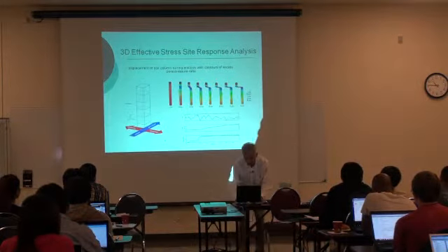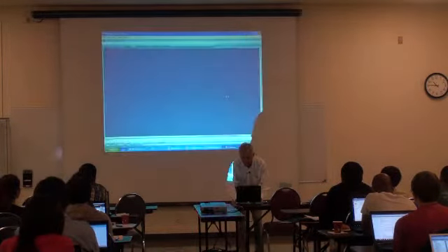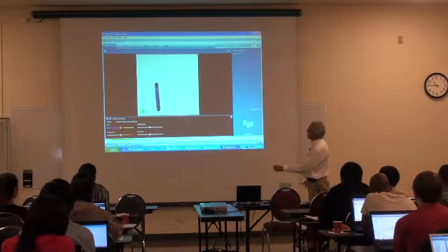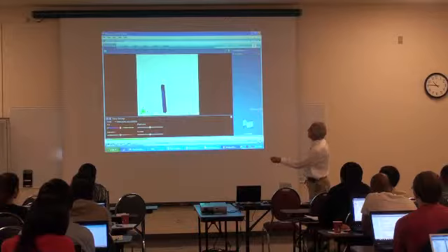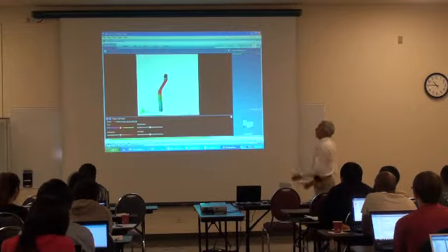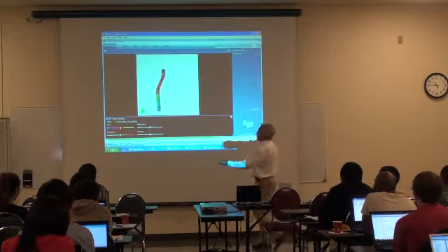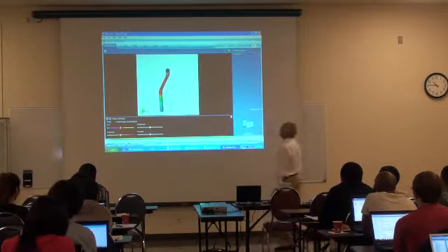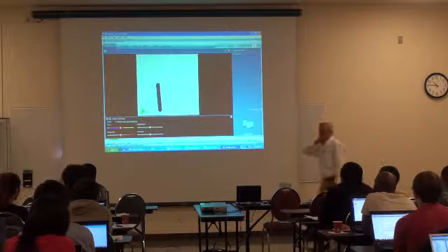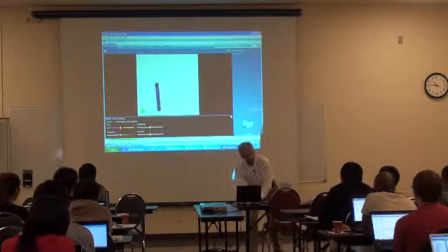I think I have here, yes. So shaking in that direction, and look at the displacement in that direction. Nothing happens at the beginning, then liquefaction, and then boom, this is going to start moving. So you have very large deformation. Actually, more permanent deformations than in the other direction. So that's why then you can start doing some interesting things.